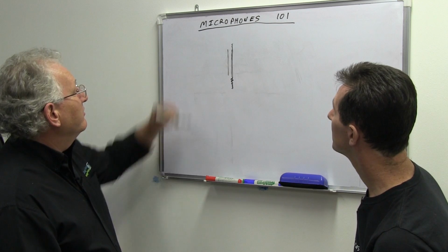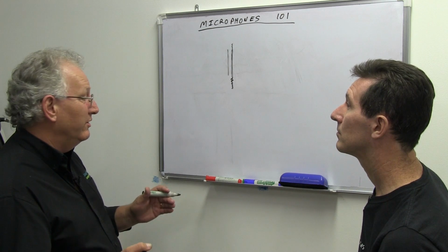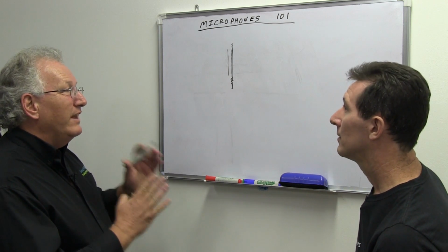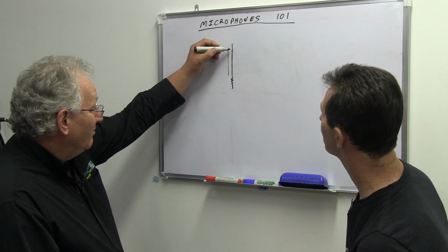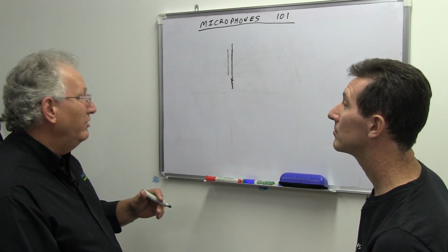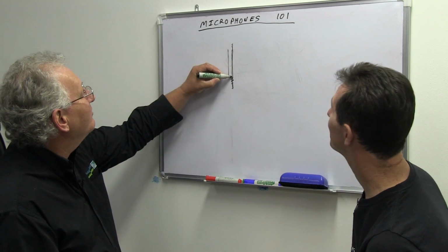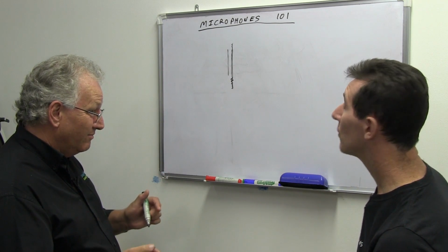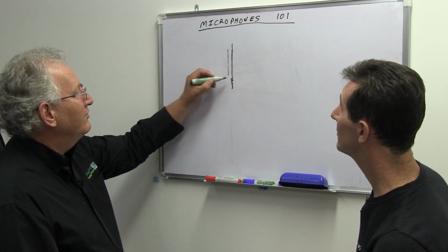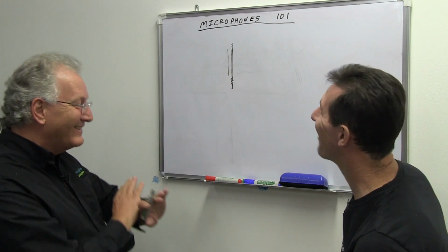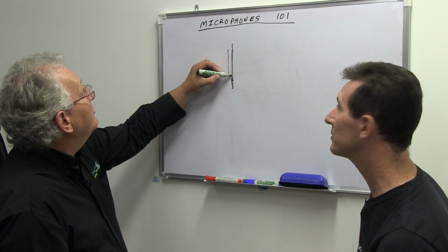And the reason for that is mylar, thin sheet mylar, is a nice material to use for a diaphragm because it's flexible but stiff, if that makes sense. Sputter some conductive material like gold. You could use aluminium. It's a bugger to connect to. Even connecting to the gold sputtering is a bit of an exercise. So it's not just in China somebody solders it on with a Hakko 936? Have you ever tried soldering mylar? No, your iron just goes straight through it. So what is it? It's usually a pressure contact.